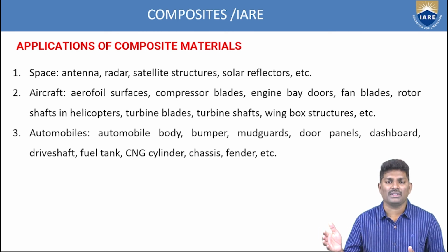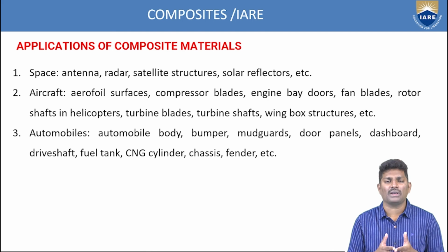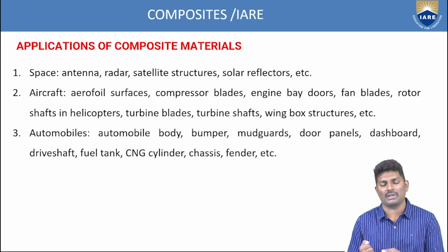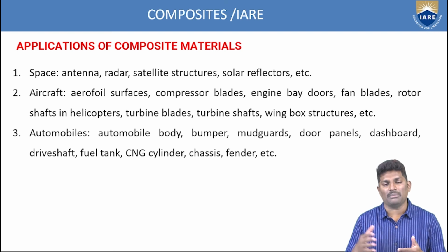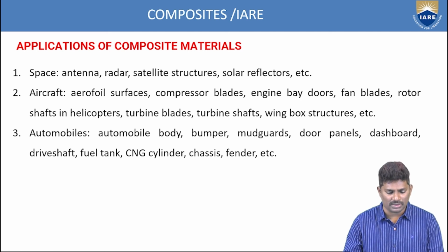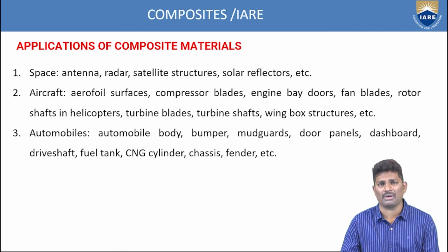The other category is the reinforcement, whether it is glass reinforcement, fiber reinforcement, or natural fiber which is available from plants and animals. Based upon different types of end applications, we are trying to select whether it is a carbon or E type glass reinforced material. Each application is very useful depending upon your properties. We have to select which property is useful to that application.